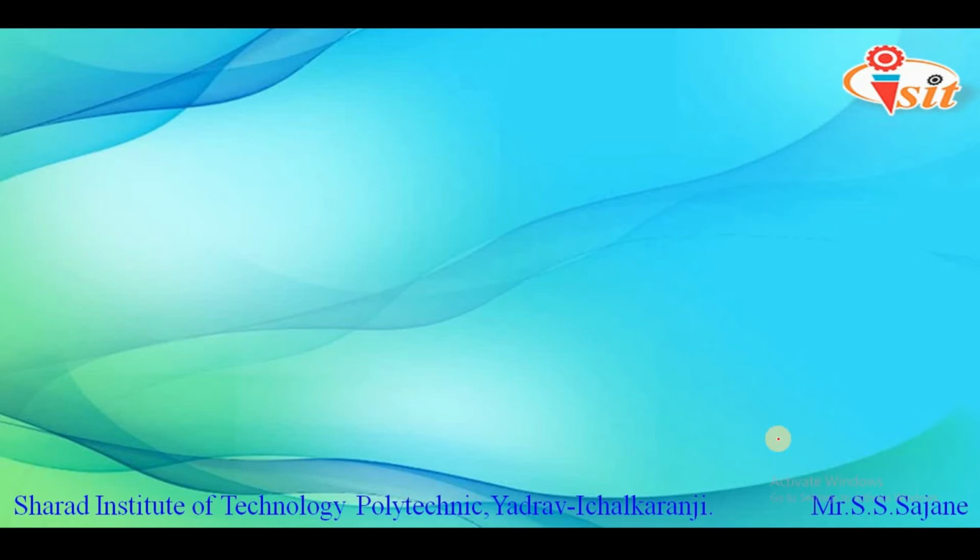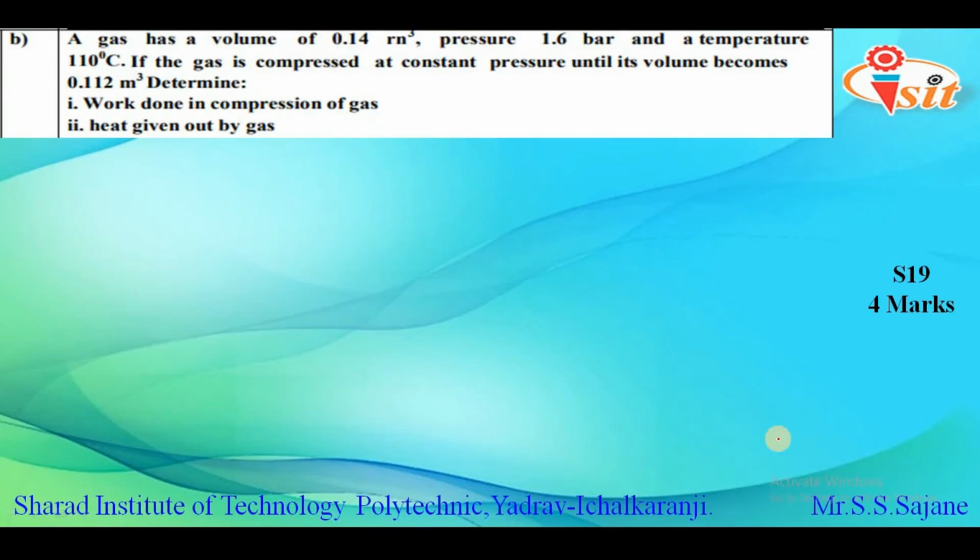Again, the next question we are having here is a numerical, which was asked in the paper summer 19 for 4 marks, and the question is as follows. A gas has a volume of 0.14 meter cube, pressure 1.6 bar and temperature 110 degrees Celsius. If the gas is compressed at constant pressure until its volume becomes 0.112 meter cube, then determine first the work done in compression of gas and second the heat given out by the gas.